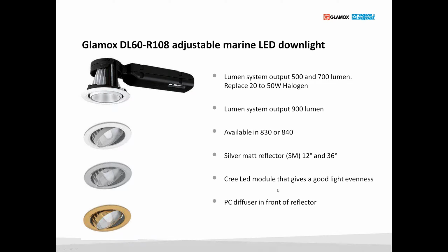On the R108 we are using Cree modules, and we are also using a PC reflector in front of the diffuser, as you can maybe see on these pictures here. We are also going to add an inner diffuser over the LED module, because when you're out visiting the customers, they look at the downlight when it's not lit, and they look at the yellow thing inside, and they don't want to see it.